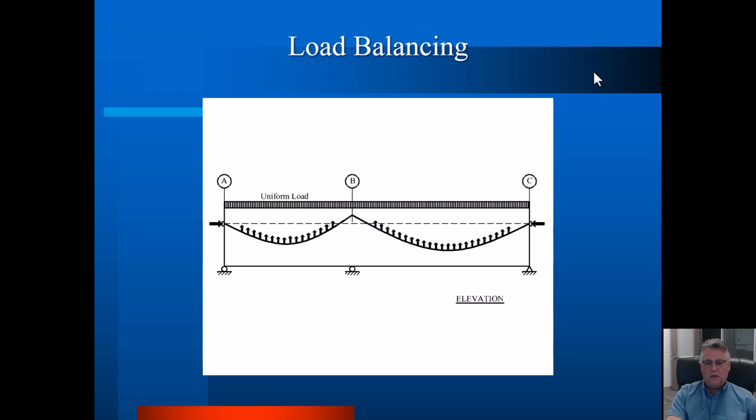You know, we can spend the money, put the post-tensioning in to resist 100% of the dead load and try to make a completely flat system under its own dead weight, or we can use somewhat less. Most of the time, it's the most efficient to use somewhere in the 70 to 80% dead load, concrete load balanced percentage. Changes job to job and person to person, but that's the general area. That's the window that we usually work in.